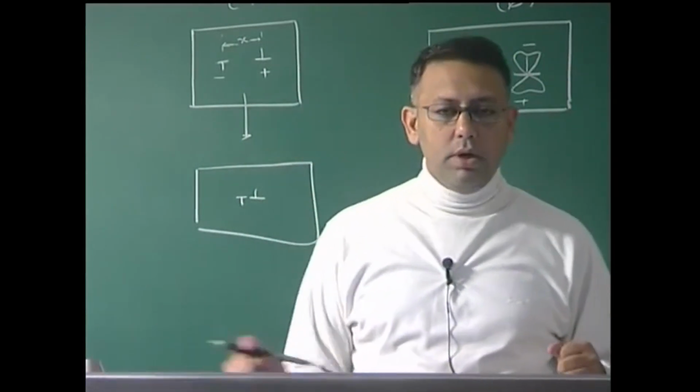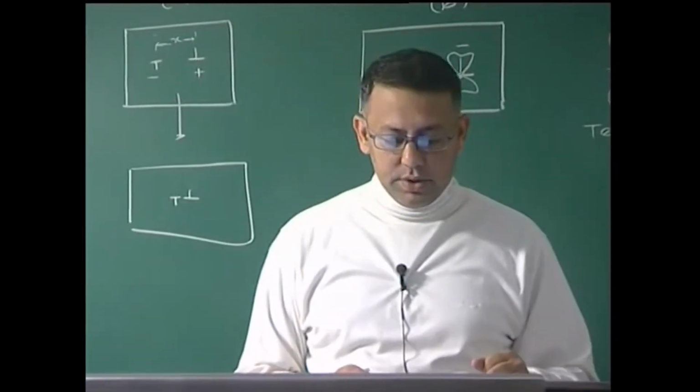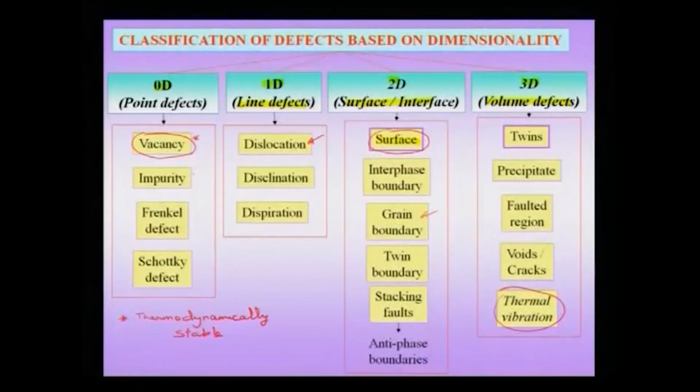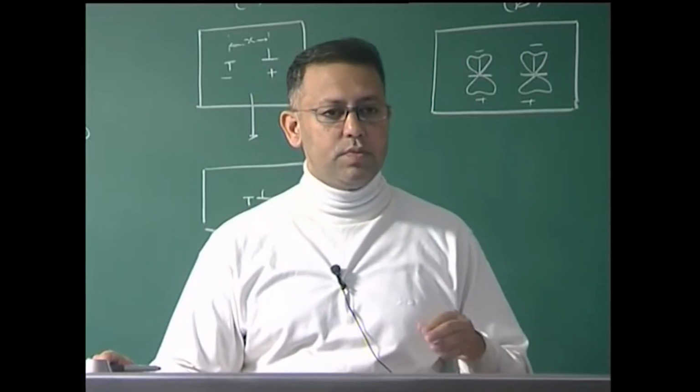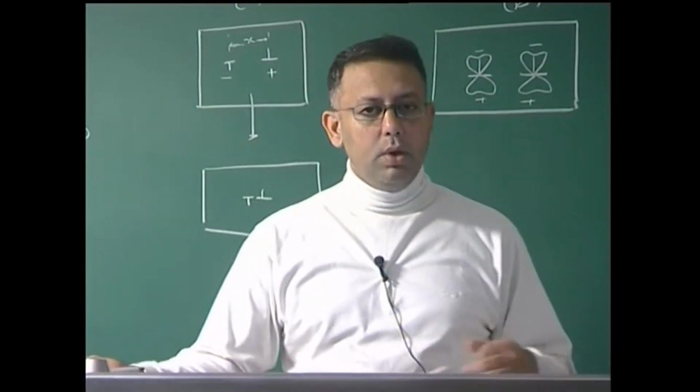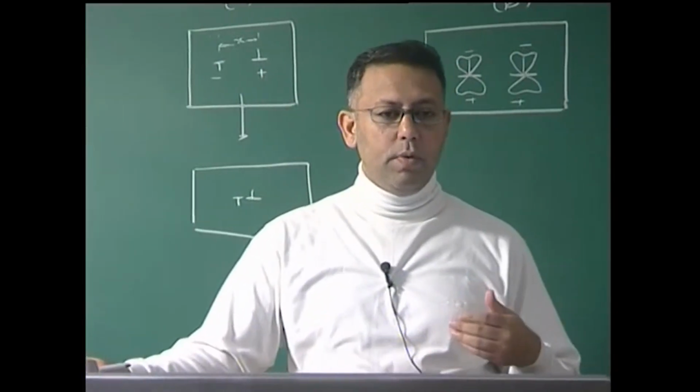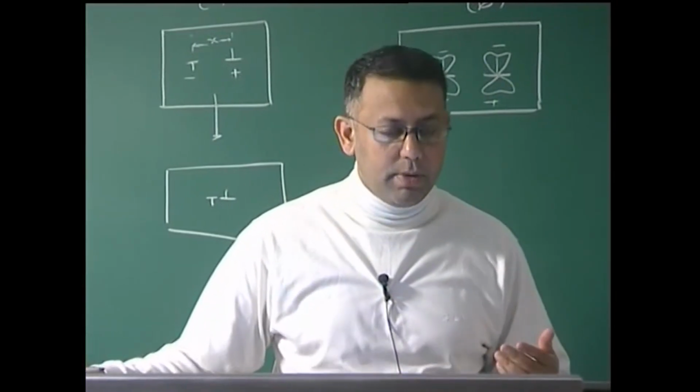The other important zero dimensional defects which we need to consider are what we might call impurities, which is a casual term; we can think of them as substitutional or interstitial atoms, and that is a very important kind of defect. Though we are talking in terms of defects, these could intentionally be added to improve properties. For instance, in steel we add carbon to increase the properties. In other words, if you want a harder material, then I may add carbon to it.